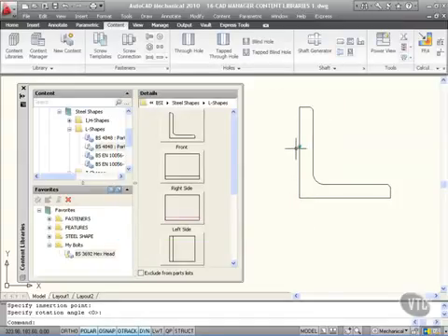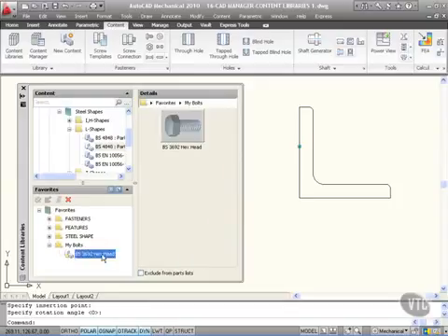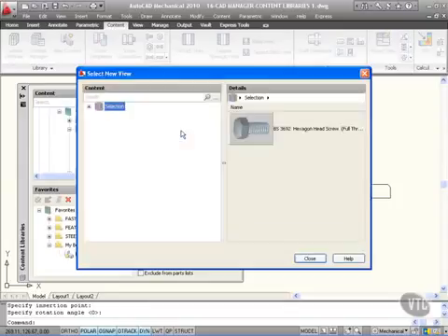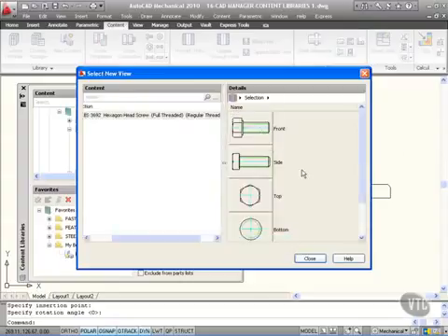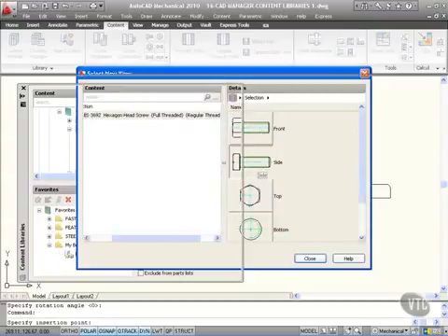I've even got, can you see the part symbol there, ready for my parts list of my bill of materials. Now I can actually add any of these to my favourites. So you can see there I've got my bolts and I've got a BS 3692 hex head already set up. If I click on that now, you can see there I click, and what I want there is, let's say, a particular view of that. So I click there and I want a side view of it, let's say.